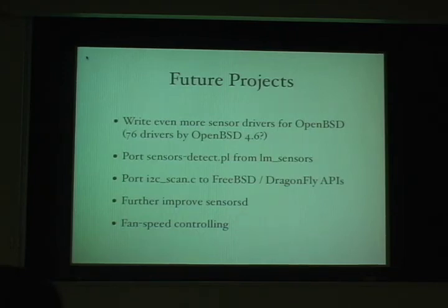And the chips actually have too many different interfaces to allow you to do fan controlling. So the fan controlling can be done on the chip itself. And some chips provide 5 different levels, so basically you can specify 5 different voltages that will be supplied when 4 different temperatures are crossed.